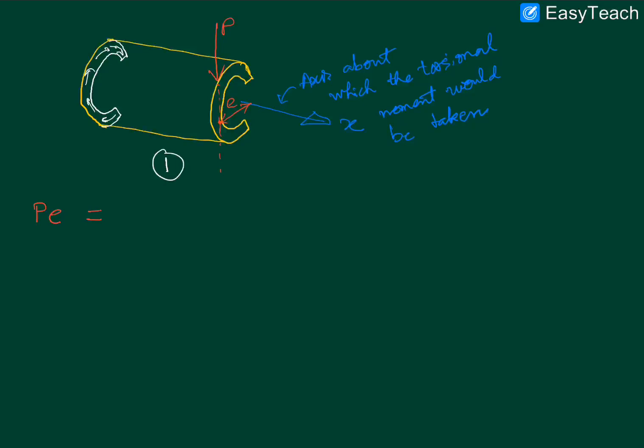So how can you write the shear stress distribution contribution? Sigma xs times the area. When we say an area, it's an elemental area, a dA, and we have already seen that the dA is nothing but t R d phi.